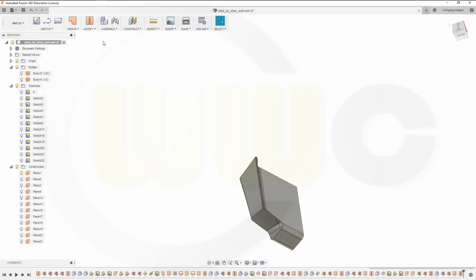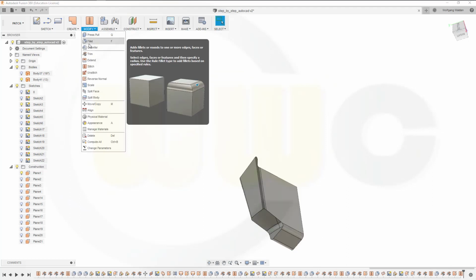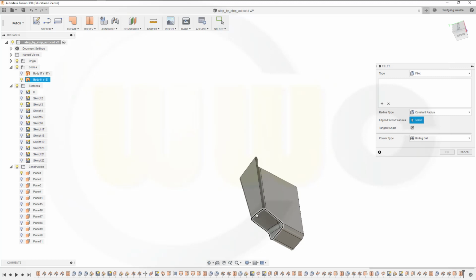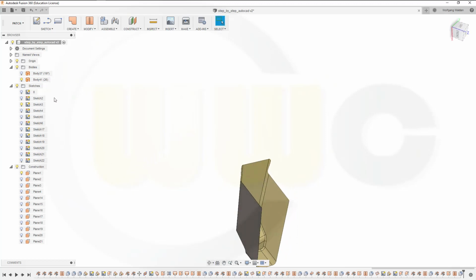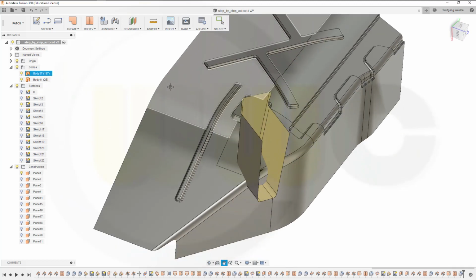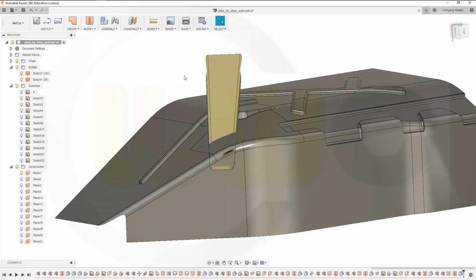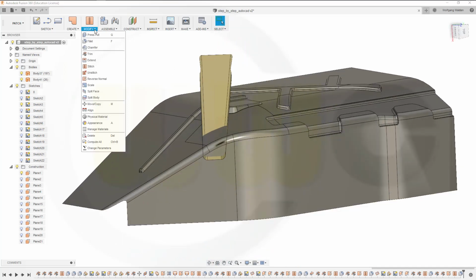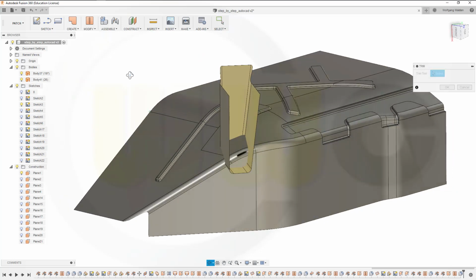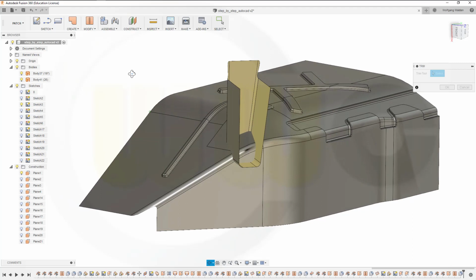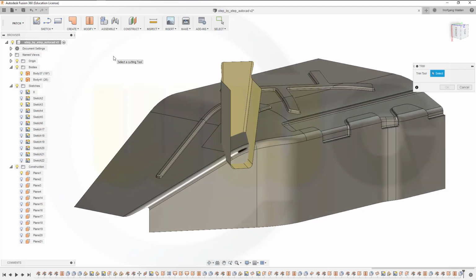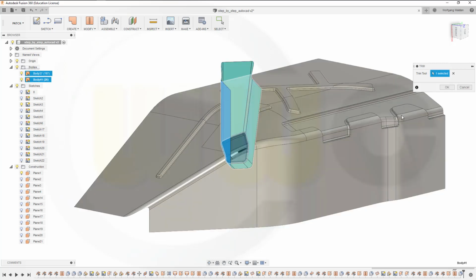Okay, now I could do a fillet on that edge and go for 3 millimeters. Nice. Now bring back our body and trim once more. Go for modify, trim. I want to trim, what's the tool? That's the tool. I want to remove this side.